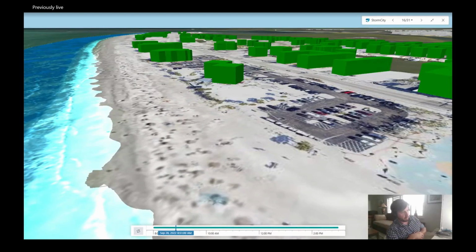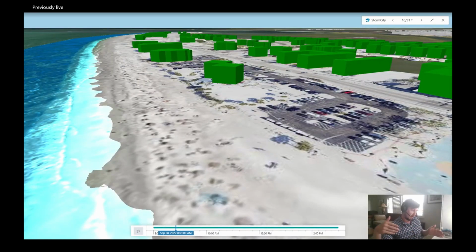To generate a directional mesh, you're going to need a center line. That's one of the things that you might not always have. There are ways in GIS in which you can pretty rapidly make them. But once you have that center line, because you don't just want to use a rectangle, you want it to be able to do the bends of the flow path. So you don't want to use an adaptive mesh. You want to use a directional mesh ideally for a river, and for a road, you want to use a rectangular.